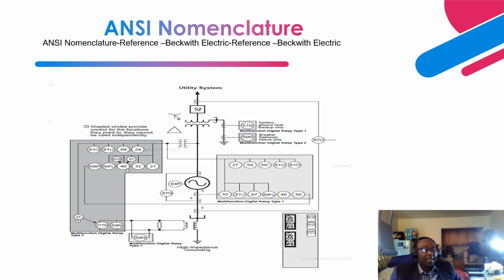Next is 59, and this is an overvoltage element. Let's say you have an overvoltage condition at the terminal of the generator, due to a load rejection or due to inappropriate operation of the excitation system, or due to inaccurate sensing of voltage. Then this is the protective relay that will sense it.